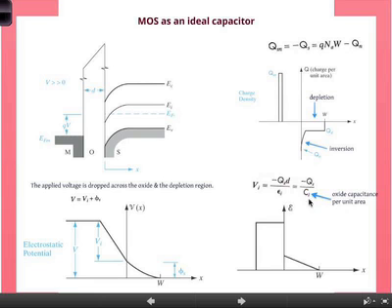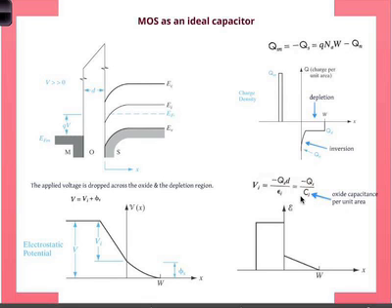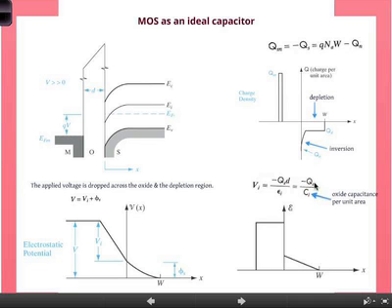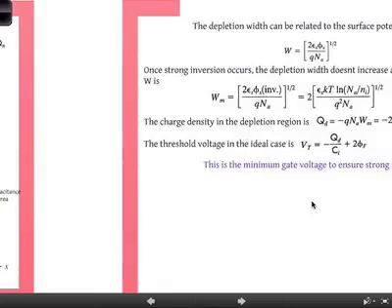And you can define essentially an oxide capacitance per unit area. And we will see this becomes an important factor in transistor design for circuits. Okay, and this is something that device designers actually tune very, very carefully, and we'll talk about that also. Okay, so this thing, keep in mind. That's the oxide capacitance per unit area.